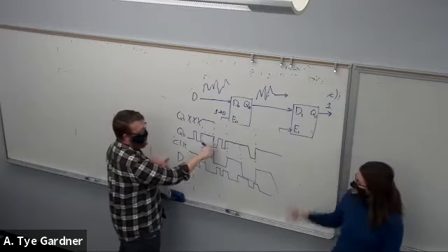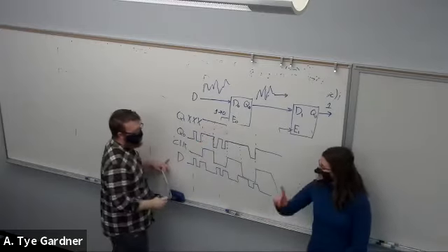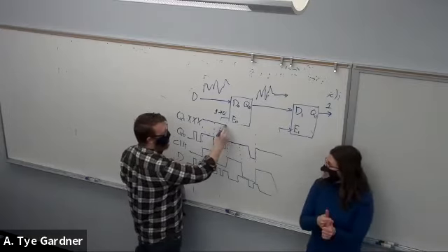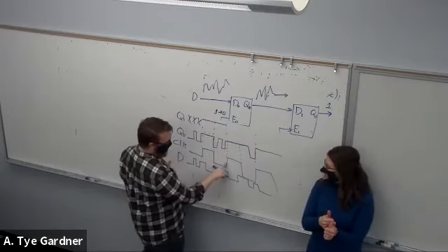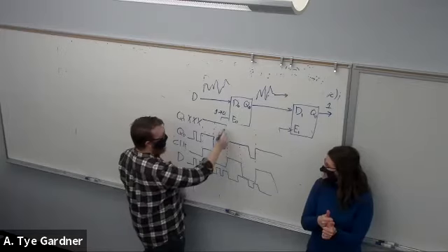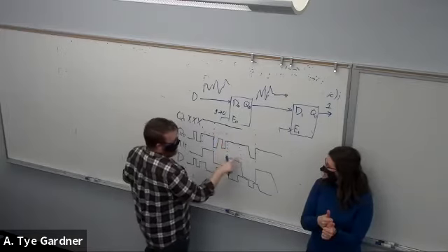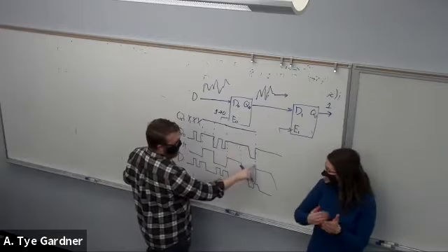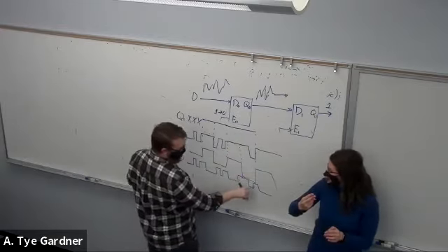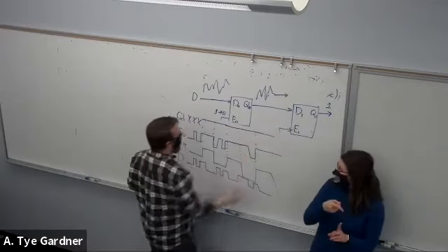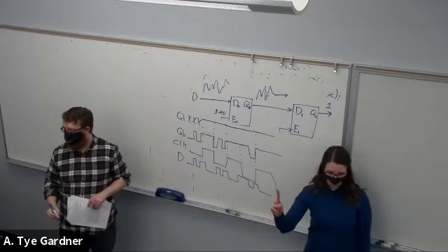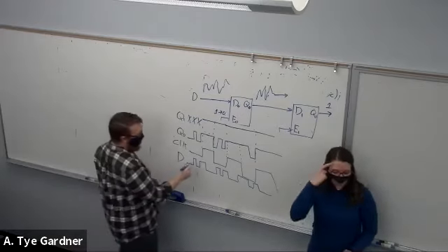Now the clock is back low, so we get to ignore it. Clock goes back high, we follow. So rising edge of clock, we get here, we get another 1. Drops low, we get to ignore it until it goes back high. Clock rises, and at this point, rising edge of clock, it's still 1. Well, look, Q1 is just 1 that whole time. Why? Because the rising edge of the clock,